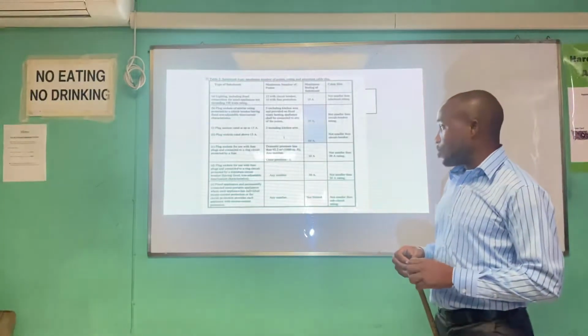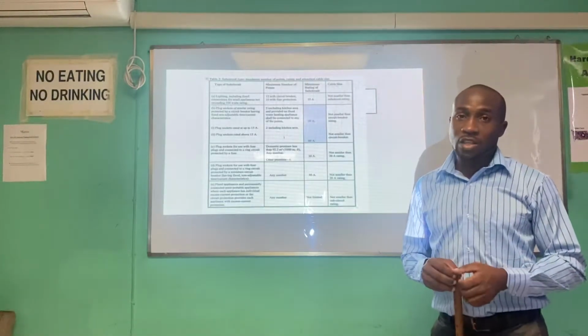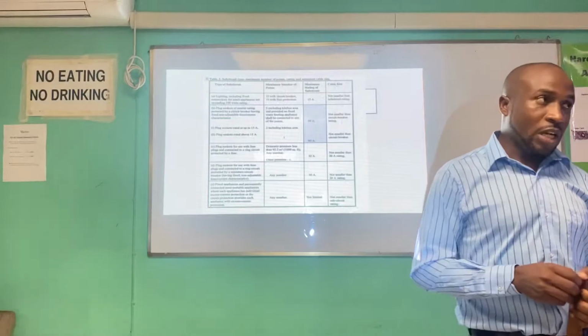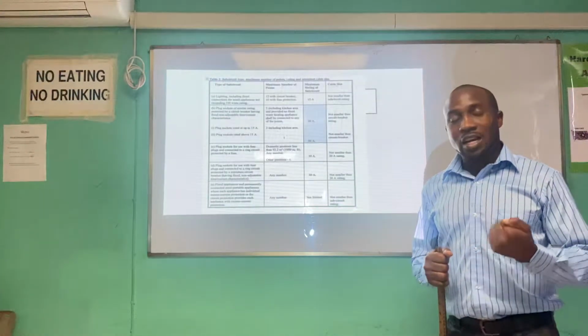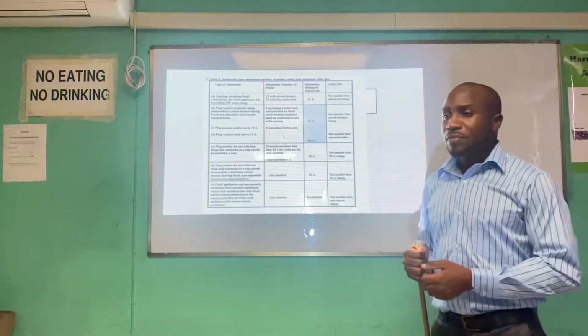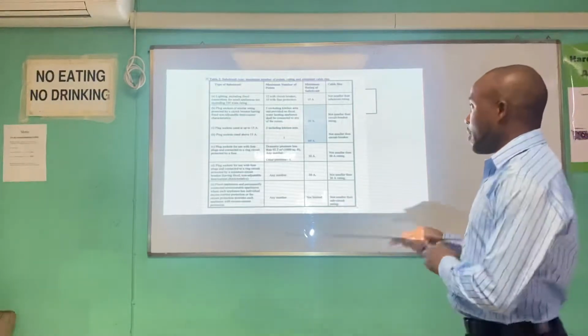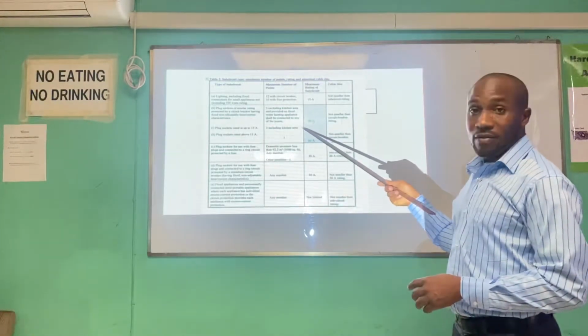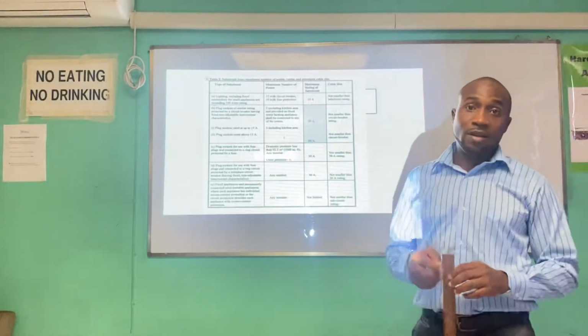So what most persons do, which we find is pretty safe, is to ensure that any plugs installed in the kitchen are on a breaker by themselves and not mixed with any plugs in any other area.